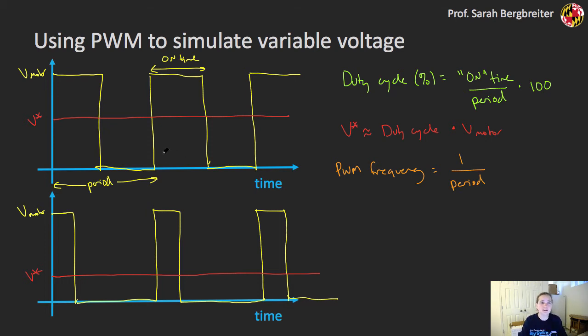We're going to use the idea of filtering. I need filtering in order to get this approximation. The time constants that are going to provide that filtering are both the mechanical time constant associated with the motor, based on the inertia that I'm trying to drive with the motor, as well as the inductance in the motor providing an electrical time constant, right? And tau in that case is L over R for an inductor.